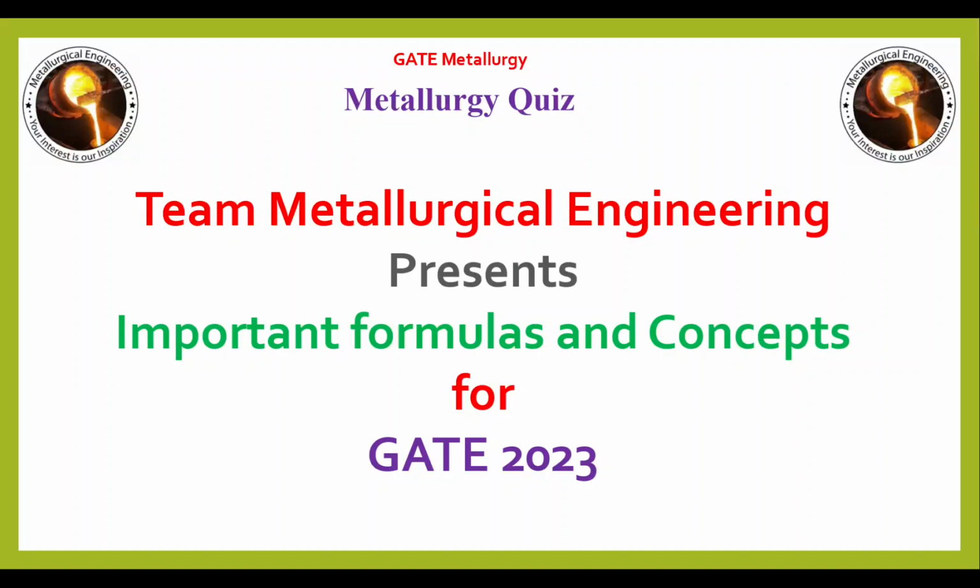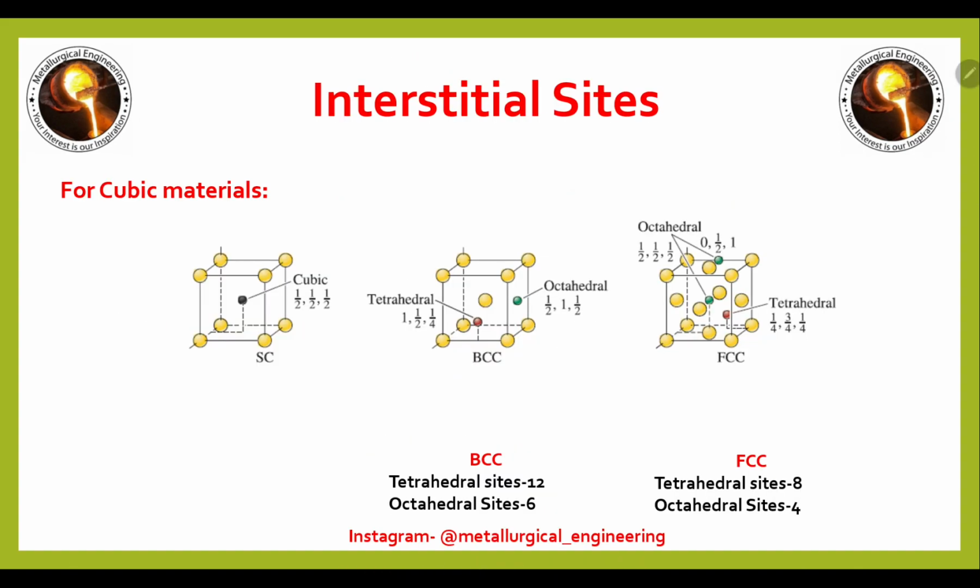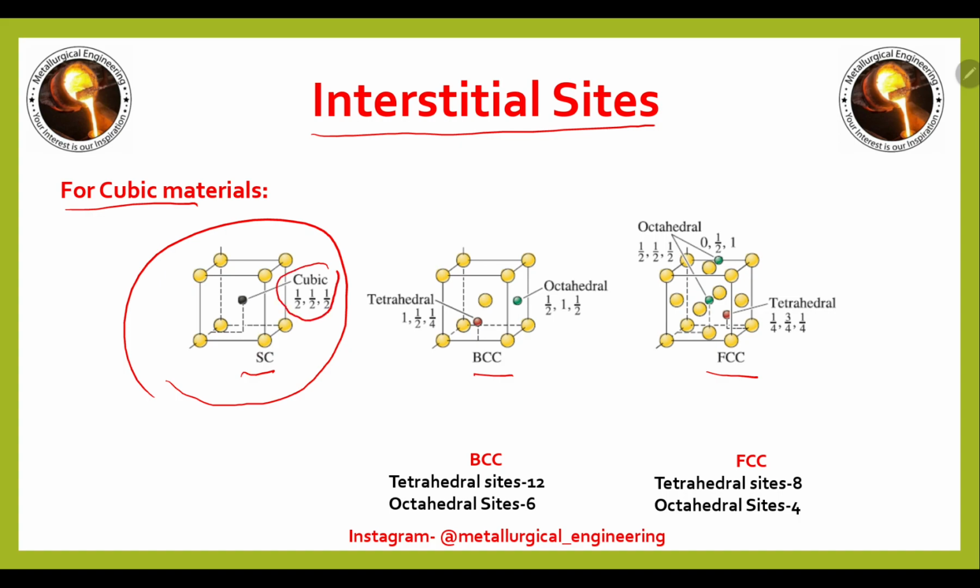Hello everyone. In this second part of the important formulas and concepts for the GATE 2023 exam for metallurgical engineering, the next topic is interstitial sites. For cubic materials we have simple cubic, BCC and FCC. In simple cubic we have a cubic interstitial site present at the center of the unit cell. The location of this interstitial site is half.